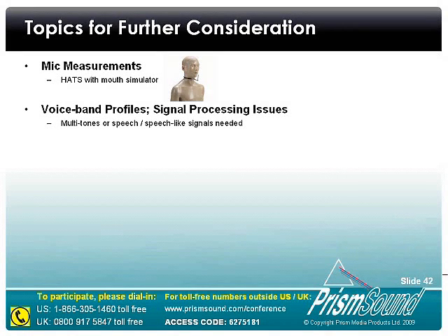A lot of the advanced signal processing algorithms in a typical telephony headset today may not allow a sinusoidal stimulus to pass through the system. So we need to use something potentially broader band and more speech-like. In fact, multitones can potentially pass through some systems, but not all of them.